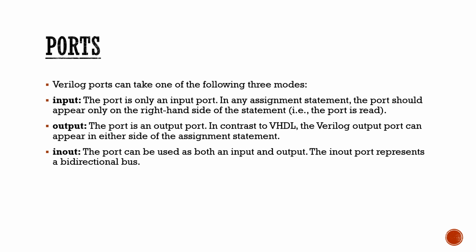And lastly, the in-out ports act as both input and output. For example, in-out data used for bidirectional communication. As an application, I can mention RAM data bus, microprocessor buses, etc. So this is about the different types of Verilog descriptions and ports.